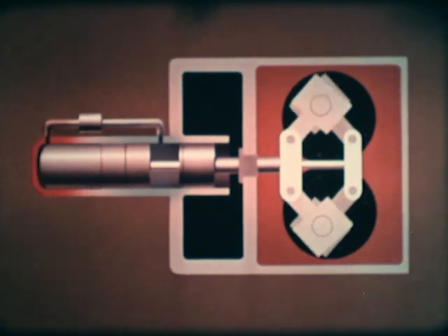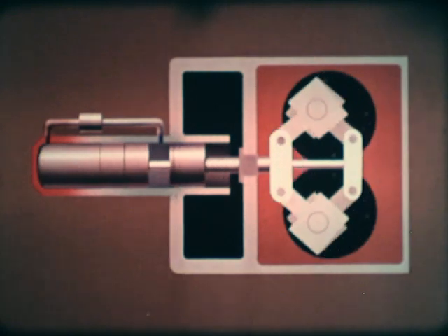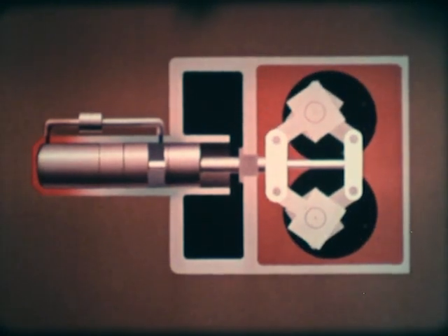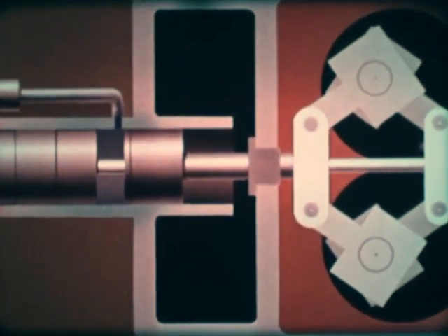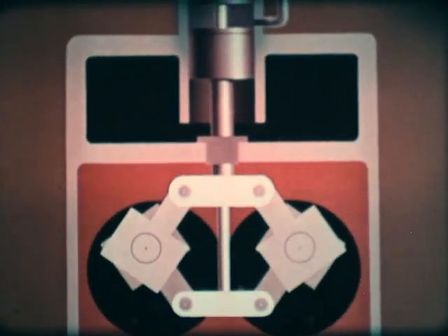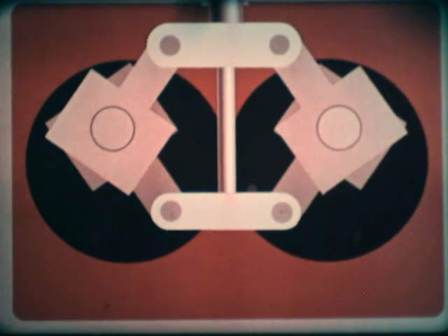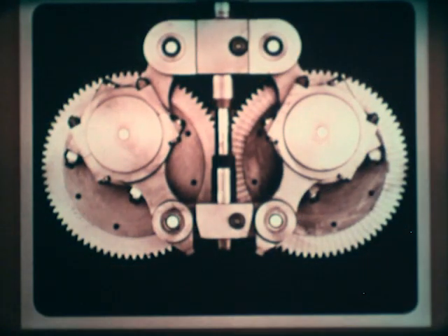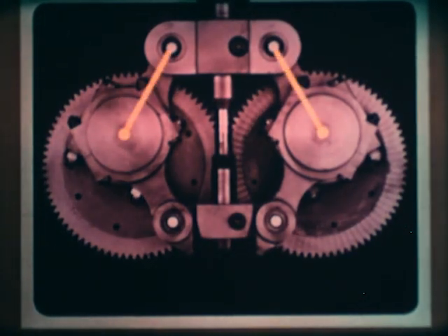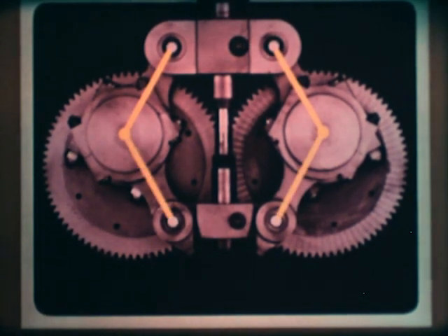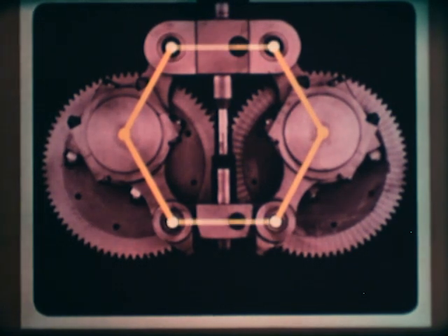This is how the rhombic drive is built up. The mechanism comprises two pairs of connecting rods of equal length. One pair connected to the yoke of the power piston, and the other pair to the yoke of the displacer piston. The yokes are also of equal length.